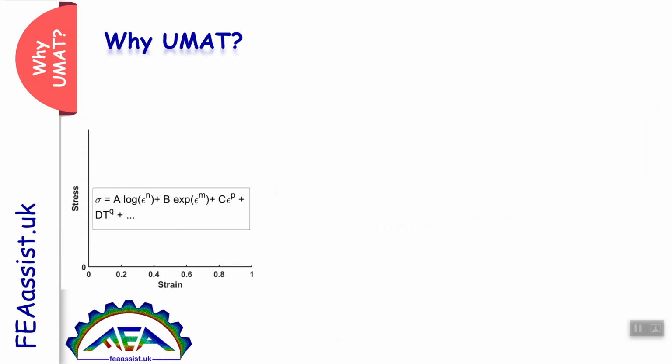So what can you do? Then you need a place to write this equation or your equations and tell Abaqus to obey this behavior to solve my problem. This is the reason we need UMAT, because our equation is new.